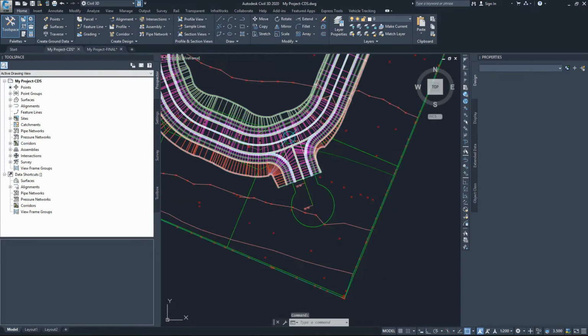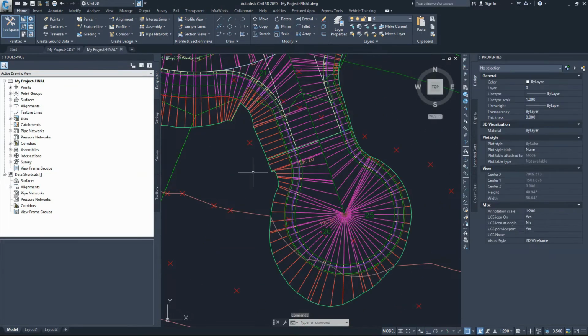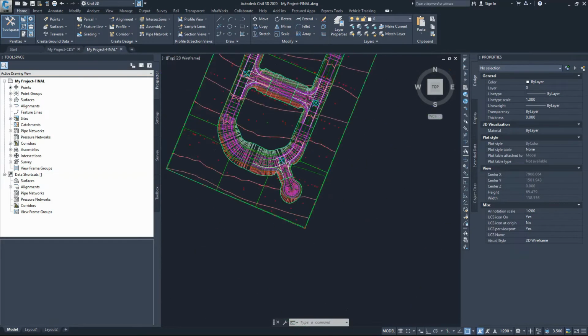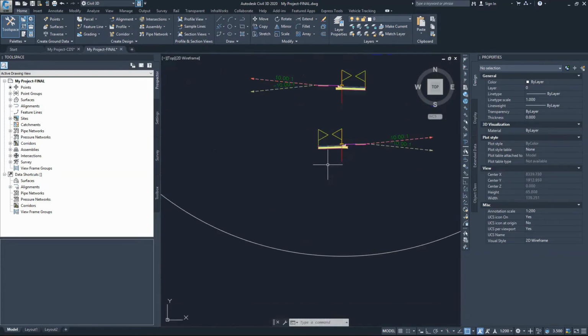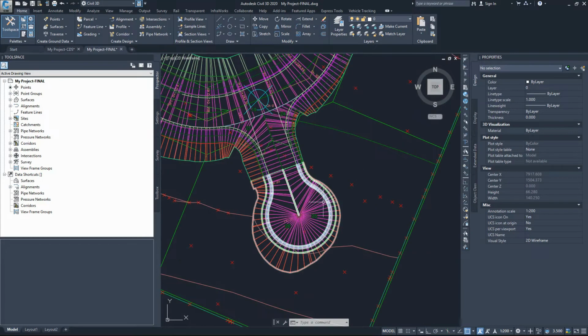So to go back to our file, to start with, we have to draw that shape because we will use that shape as our alignment. Overall, just for you to know, the design we'll be carrying out is very similar to the design of the curve return around the intersection. We'll create an alignment around this line here on the outside. That alignment will create a profile for it, and we'll use a cross section similar to the curve return cross section. One of those goes around and along this alignment here. That will create the surface of the Cul De Sac.